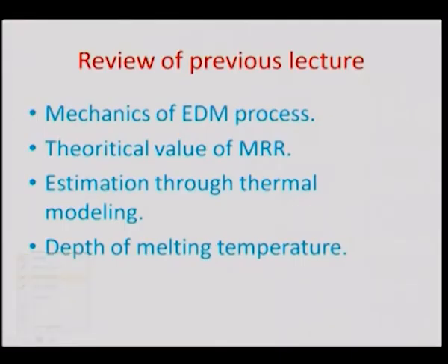For the sake of repetition, I'd like to say that this is all about the formulation of a spark between the tool electrode and the work material. The tool electrode is the cathode and the work material is the anode, and there is always a field in between, created because of a voltage gradient, and there is a dielectric medium in between. It's all about reaching the breakdown potential of that medium, so that there is an electron flux which comes from the tool side and ends in the anode side, the workpiece side.